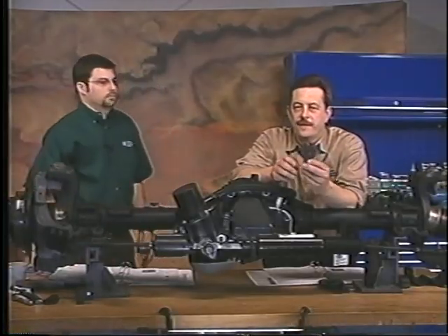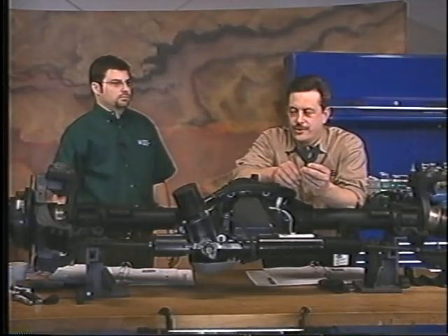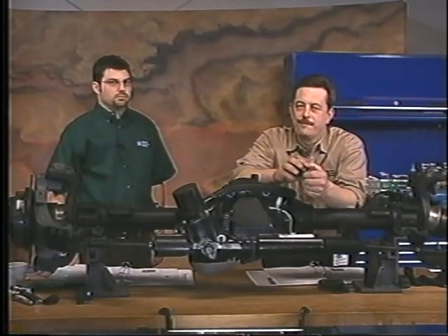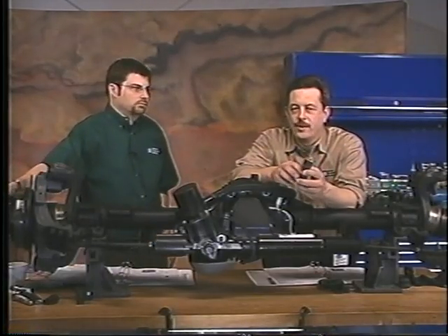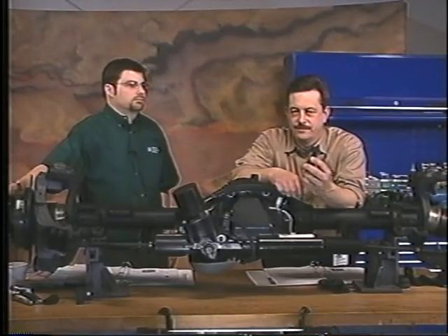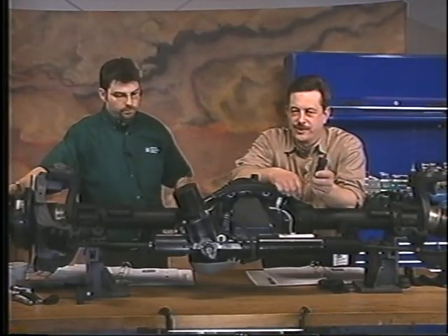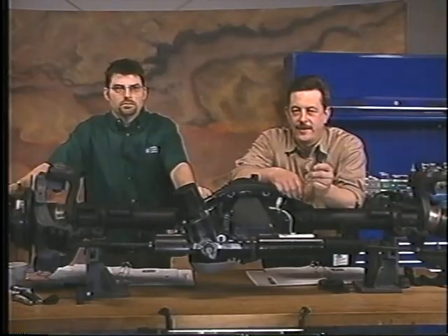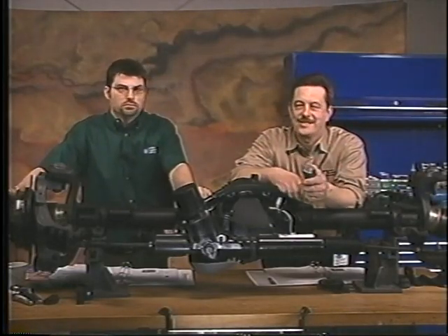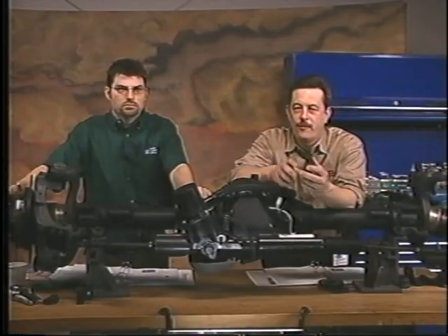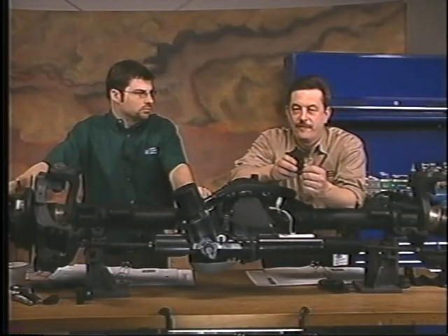Now, if you want to put the sensor back on, you're not sure of center, pretty easy to do. Just go ahead and plug in electrically, grab Tech 2, go into the rear steer area, and take a look at the analog feedback from this sensor. Okay? There's an analog signal, there's digital signals. We want to look at the analog here. Just dial that in to see 2.5 volts. It's running a 5-volt reference. So guess what? It means that's the center position. Now, I've set it up that way. Now it's ready to go back on the steering column, have the wheel straight ahead.